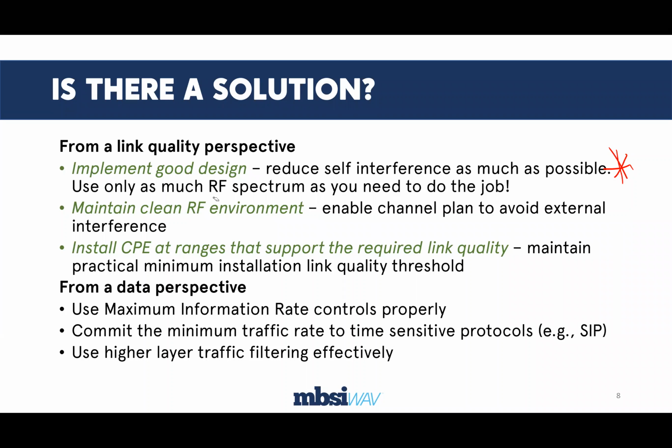The point here is that nowadays with the OFDM protocol such that it is, and the over-the-air protocols that we're using, we do now have the ability to have the CPE behind a tree or two, or a row of trees, or whatever the case happens to be, and we still might be able to make our required link quality with the CPE even at that. But we might need to do a little bit more work. We might need to make sure that the CPE is up high enough, or that the CPE is on the right spot on the house.